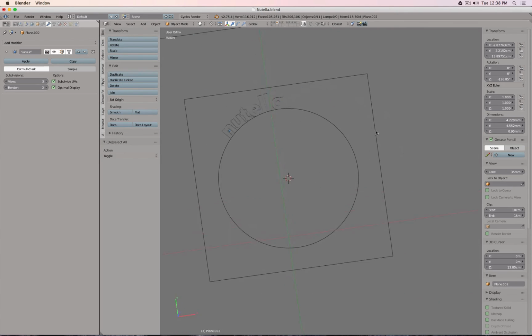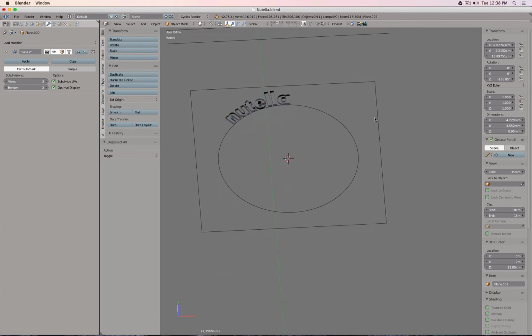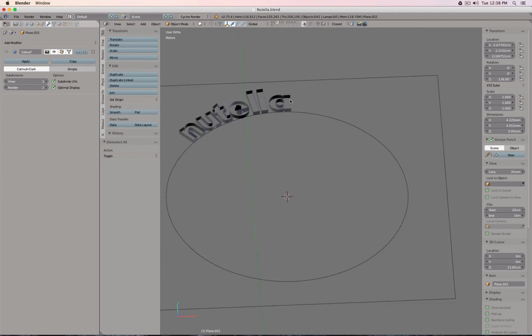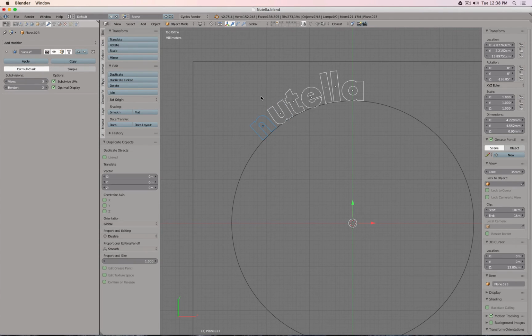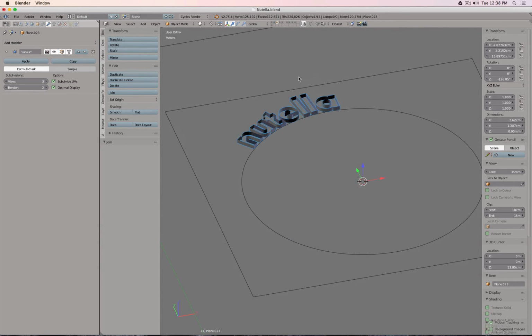Okay, so you see, that's basically quickly the way I created all these shapes. Now, these are individual objects, and when I would like to cap everything, I don't want to have to add too many commands for the Boolean. So what I do now is the following. I simply Shift D, escape, make a copy, and then Control J and join everything together. So now this is one object.